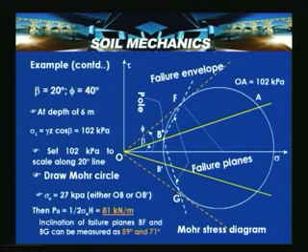active thrust. In this problem, keeping the soil properties under consideration and the geometry of the slope surface, we calculated the earth pressure coefficients. From there, we solved by computing the earth pressure ordinate at a depth z equal to h equal to 6 meters, and then the active thrust was calculated. The same problem we tried to solve by using the Mohr strength diagram.